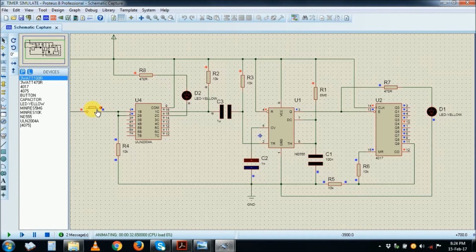Remember, when I go to number 1, QCO, which is pin number 12, goes low. Right, step that, you see now it changes. And now I'll show you what I mean by if you continue pressing here, what happens with this LED. It stays on, but this one will just come on and off. It will not remain on, because this is a monostable circuit. Right, so I continue pressing. That D1 is only gone on and gone off, but D2 is still on because I am still activating the switch. If I release, D2 goes off, but nothing happens here because it has executed that function.